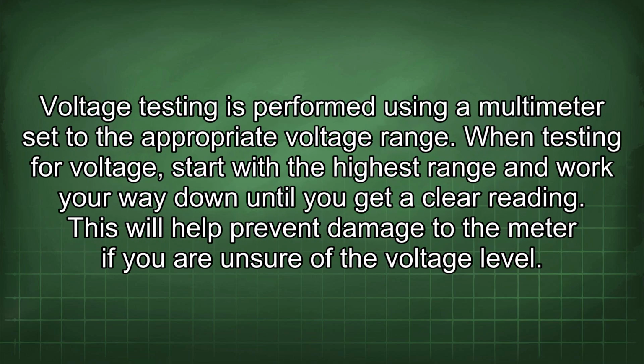Voltage testing is performed using a multimeter set to the appropriate voltage range. When testing for voltage, start with the highest range and work your way down until you get a clear reading.